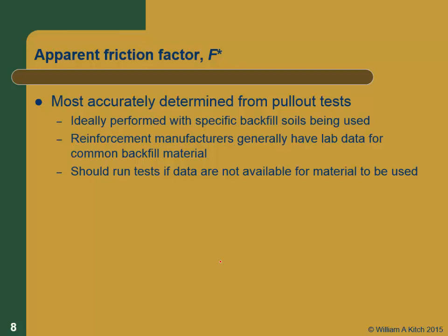If you're going to be using some material that's not been tested with, you definitely should be running tests. And if you've got a really big project, I would probably do it even if you're using the same material, because you can definitely justify the costs. And you might actually be able to do a more cost-effective design, because the numbers the manufacturers are giving you are conservative. So there's definitely good reasons for doing your own laboratory tests on any significant project.